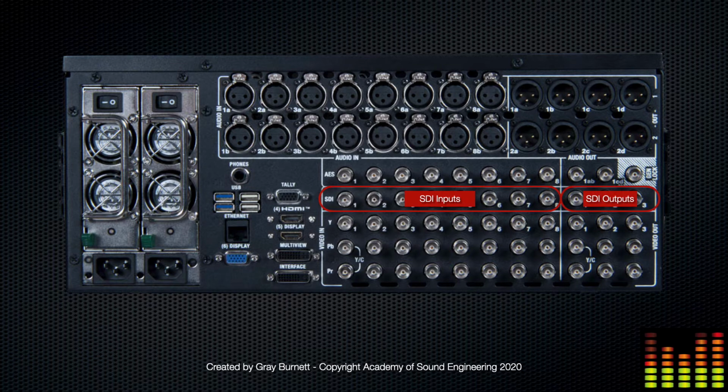Then we've got our SDI outputs. This is where you connect your output ingest or video monitors to view the broadcast or the TriCaster's output. These all output program by default. To have program, preview, and program clean or other outputs fed to separate SDI outputs, you need to configure this in the hardware configuration window. In our setup, these are again connected to our SDI switch, allowing any copper or fiber SDI video destination to receive signal from here.